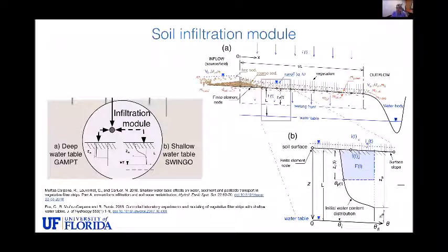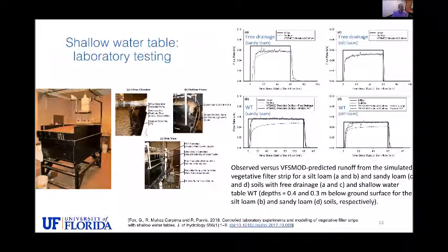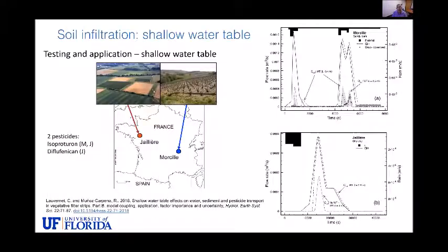This might be of interest on wetland assessments as well. This component was validated in the lab with soil boxes where we could control the depth of the water. Gary Fox did this analysis and compared it with model results. We also applied it to field conditions, in this case in France, under flatlands prone to a shallow water table, and more sloping lands with coarser soils, which had less.